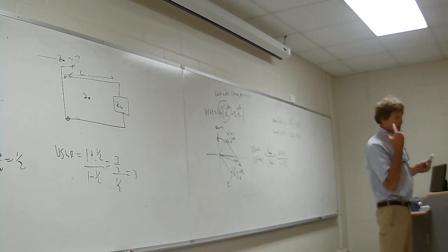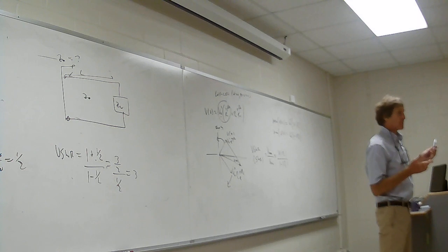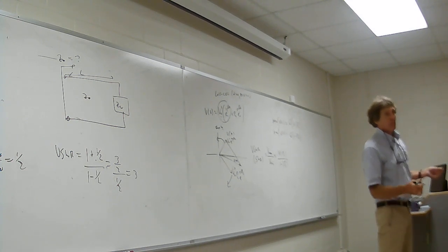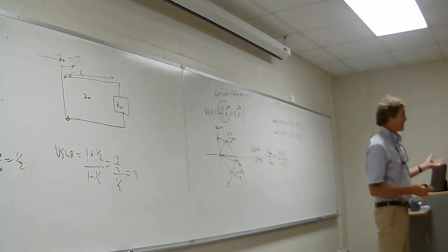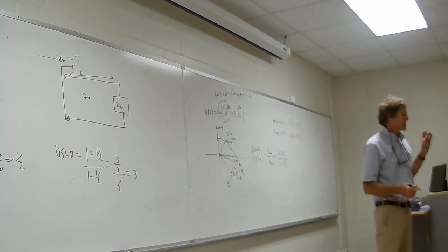And he says, listen, you need solder ball, can I take it out? Yeah, get rid of it. So he gets a solder gun, melts it, gets rid of the solder, puts it back together, measures in standing wave ratios like 1.1. Except, whew. Now the guy that built it didn't know a large solder ball could have a problem. But I hope all of you do. Have you been told to use a minimal amount of solder and always have minimal lead lengths?